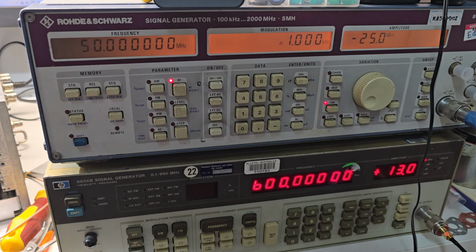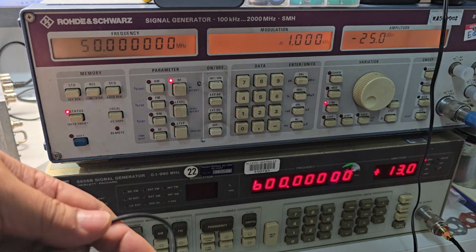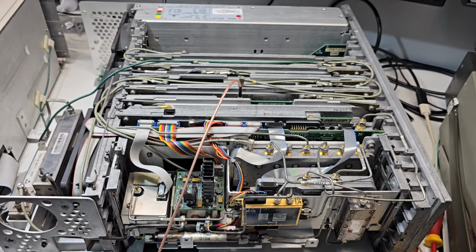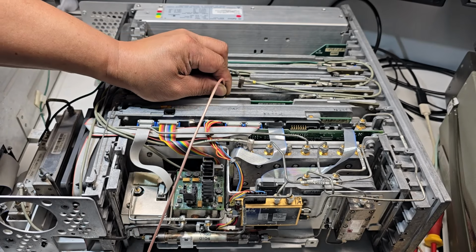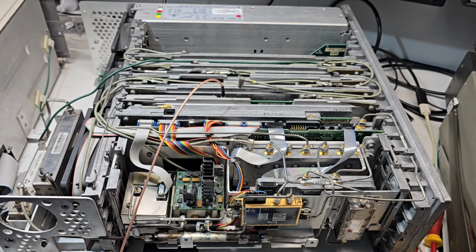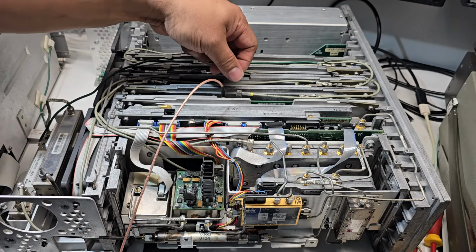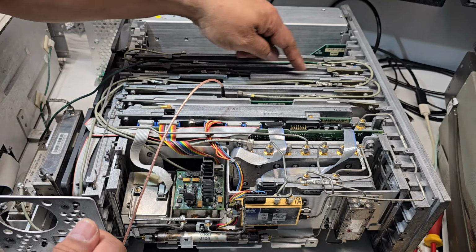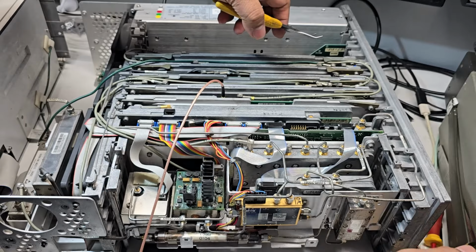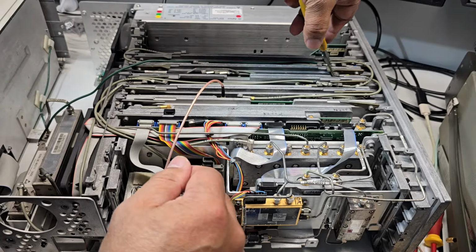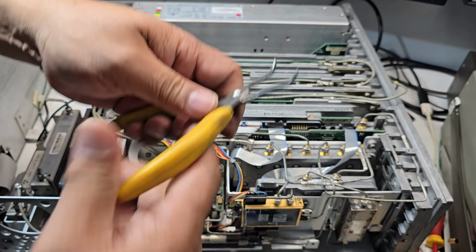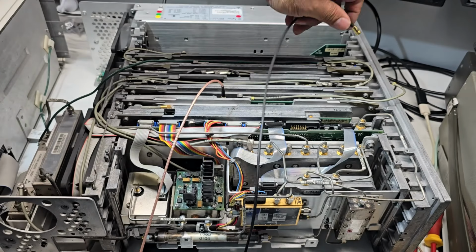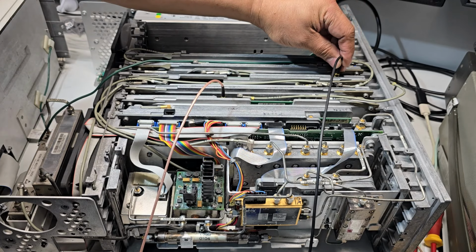So what we're going to do is we have this cable here, and we're going to inject this one. So I'm going to remove this one, and I just place this one into the 300 meg, so we can also monitor the 300 meg on the spectrum analyzer. The 600 meg, which is going into this module here, I'm going to remove this one. Okay, so that's from the 600 meg, and we're going to inject a 600 meg 13 dBm signal here.